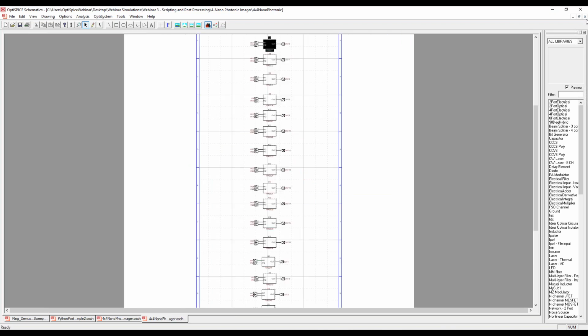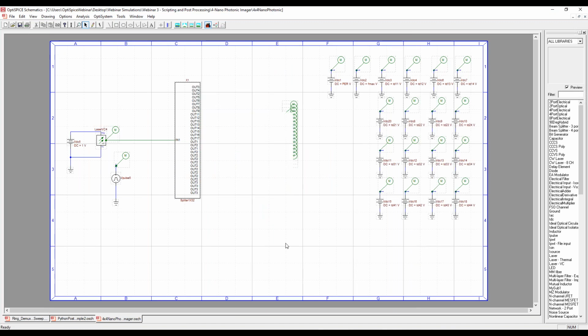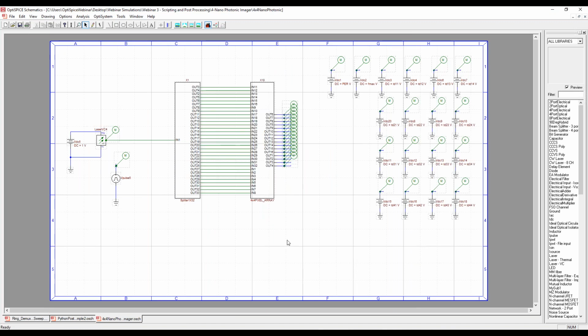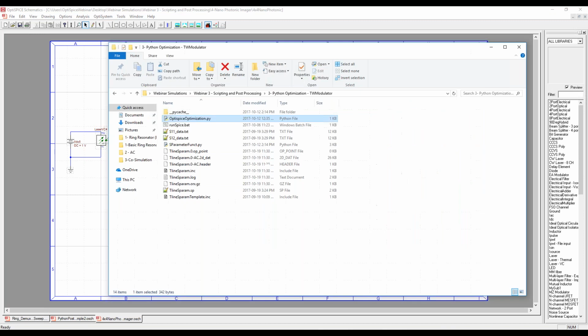So as each signal is going to be traveling a different distance, the difference between the chirp signals are going to result in different frequencies. Then by looking at the frequency, we can tell how far the light has traveled. For this one, I'm actually not going to run the simulation. I'm just going to basically show you the result.